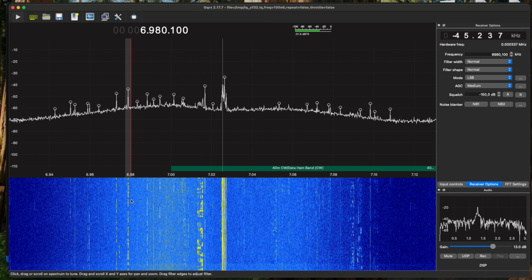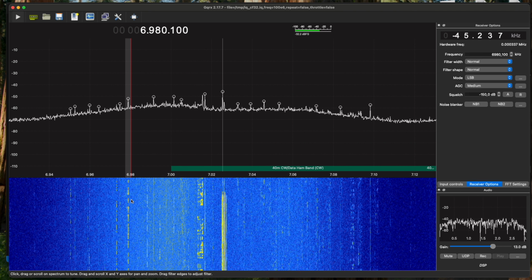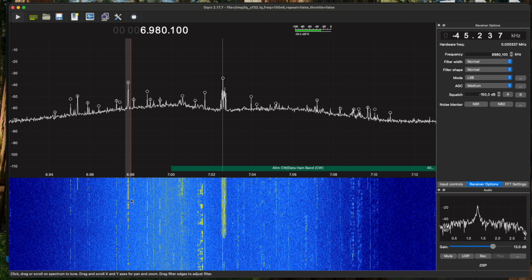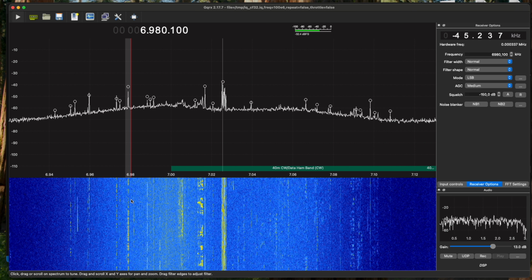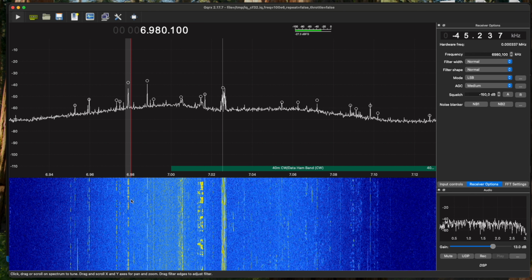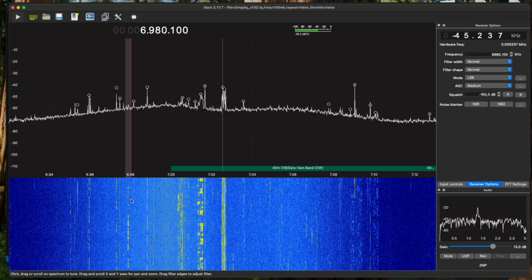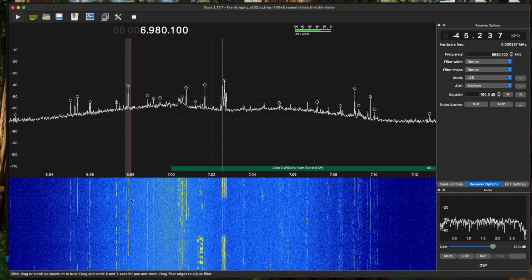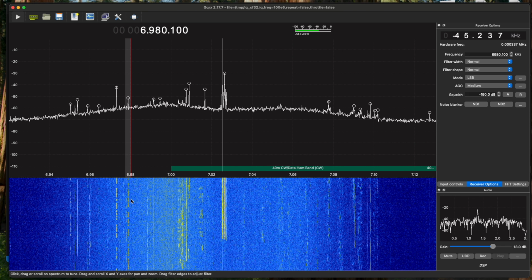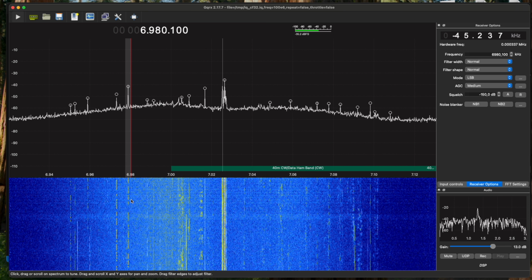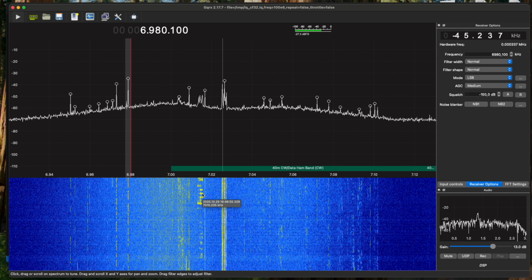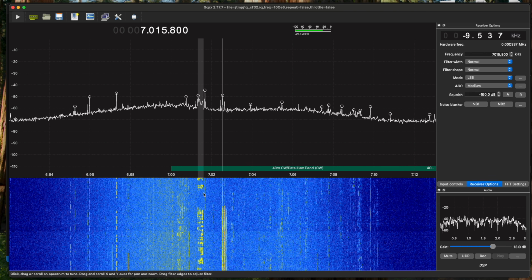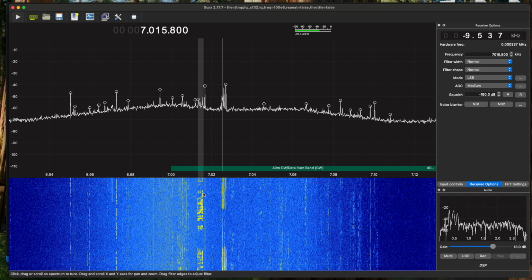In the 6502 firmware for the PhaseLoom, I've given the SI5351 frequency selection a complete overhaul, since changing only the multisynth values meant either a bad frequency resolution or an incorrect phase offset, resulting in bad mirror rejection because the Q channel didn't have exactly 90 degrees offset. By only changing the PLL and allowing it to use a fractional divider, the multisynths will always have an integer divider, so we get a precise 90-degree offset no matter what the PLL is set to.